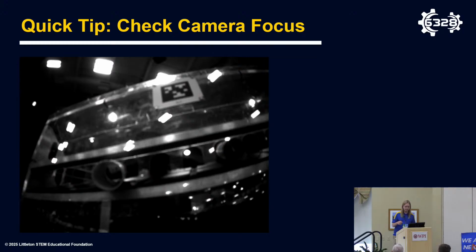It's really important to focus your cameras ahead of time and secure them in place however the manufacturer recommends. Generally, it's also good when you're focusing cameras to bias towards a slightly farther distance if you're trying to do global positioning, because even a tag that is closer, if it's slightly blurry, it's large enough in frame that generally you won't have trouble detecting it, but it's more of a concern at greater distances where you'll lose that detection if you're focused too close.